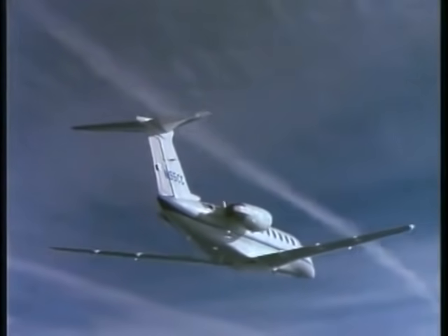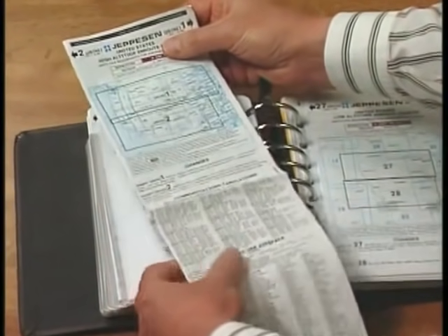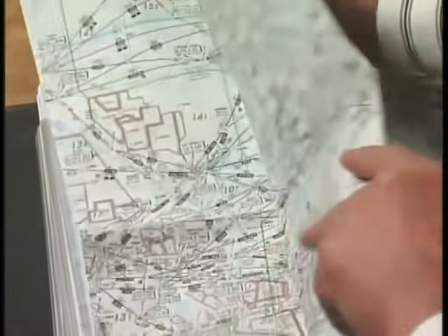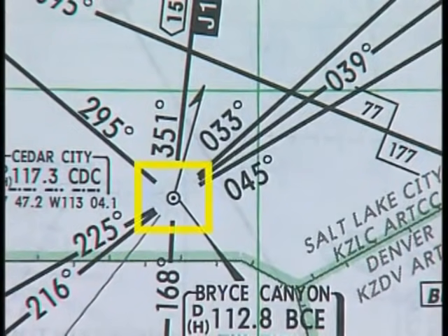The next area we'll cover is the high-altitude charts, and some of the items which appear differently on them. Since these charts cover portions of the Canadian and Mexican high-altitude structure, information about airspace variations is provided on the front panel. A primary difference between high and low-altitude charts is that nav aid information is presented in a different form. For instance, the compass rose that usually surrounds VOR stations is not shown. However, the magnetic north barb is printed for use with the Jeppesen IFR en route plotter.